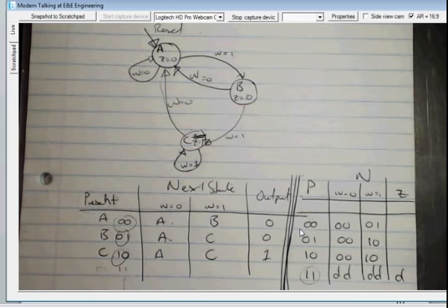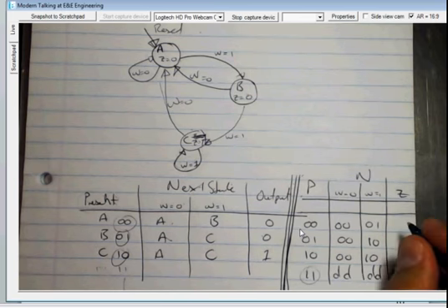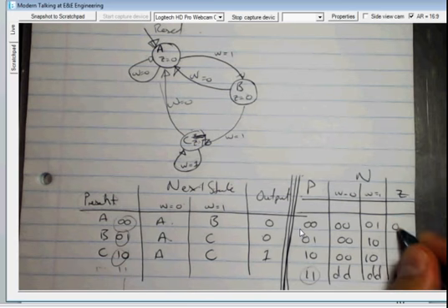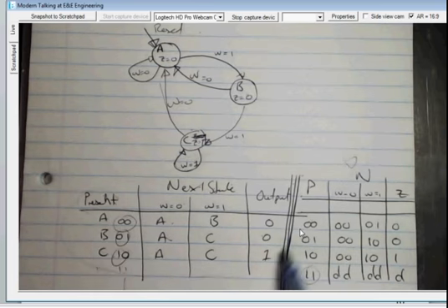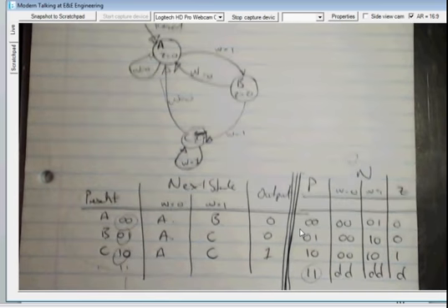We shouldn't ever enter into this state. Just be careful. Typically, if you work with safety systems, you don't want to use don't care. With a safety critical system, you want to say, if it enters this state, my circuitry is broken, which means let's return to a known state 0, 0. So this don't care is very convenient for us now. But if you go and design Boeing aircraft or something like that, you don't want to use don't cares. The output, as we said, is 0, 0, and 1 right there. So this is our state assigned table. This is our state table.